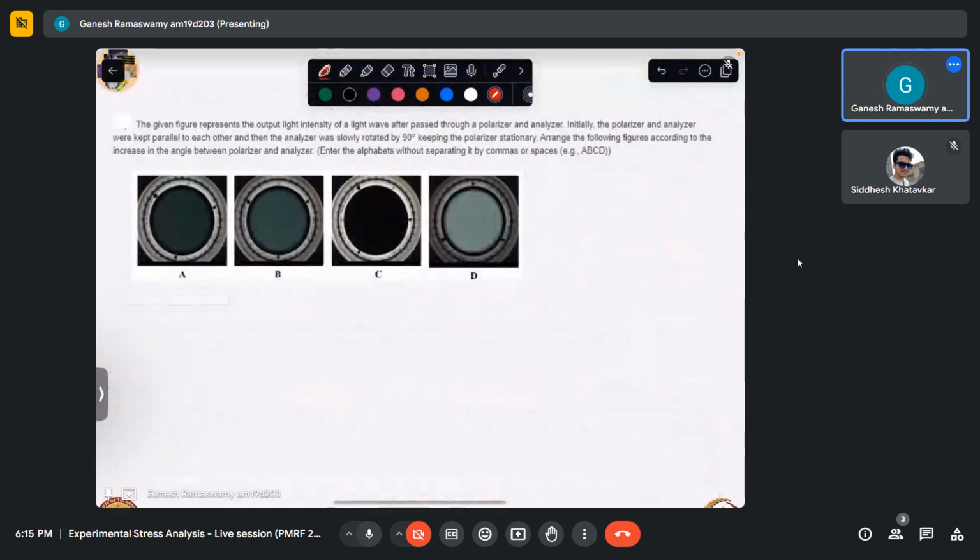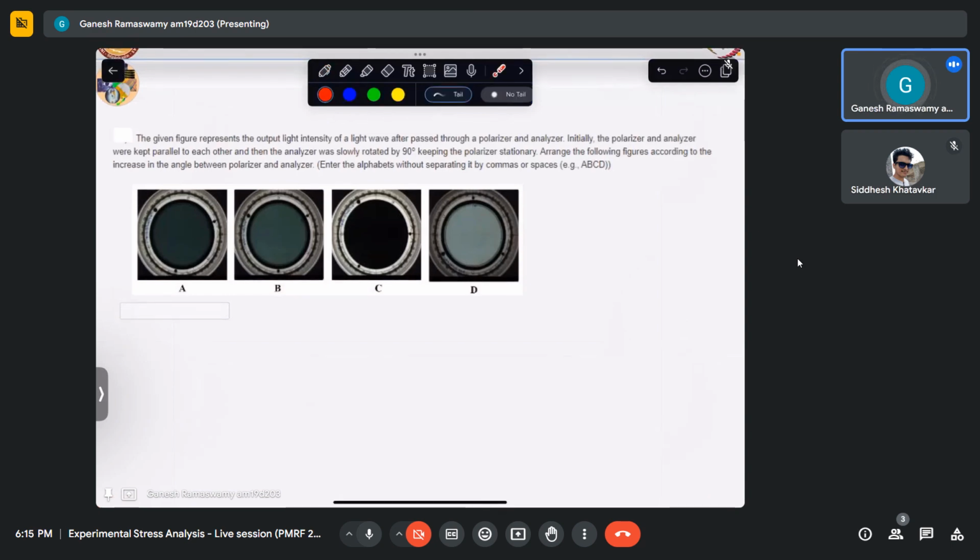And then once we were done with Moire and other techniques of experiments, we moved on to bring our focus into photoelasticity, where we generally have two types of elements. One is a polarizer, which transmits light along the polarizer axis and absorbs everything else. And then we have retarder plates that can be a quarter wave plate, a half wave plate, full wave plate, and so on.